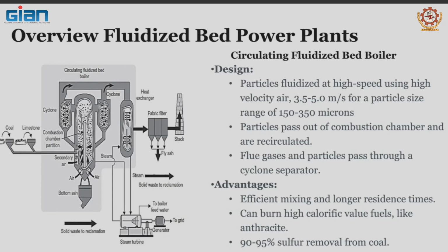You can capture some of that, but only to a certain level. Otherwise, you'll be condensing the flue gas, and if it's condensed in liquid form, it will destroy the stack and everything under it, because it will come down in the form of acids, as I mentioned.